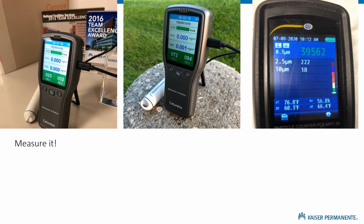The photo on the right is a particle count in a patient room. This was not during the week of the fires, it was the week before that. But this is right when we walked in before we did any of our testing or any of our fouling or anything like that. There's 39,500 0.3 micron particles. And if you do the math on that, you'll see that this patient room at rest is about ISO class 6, which is very clean.